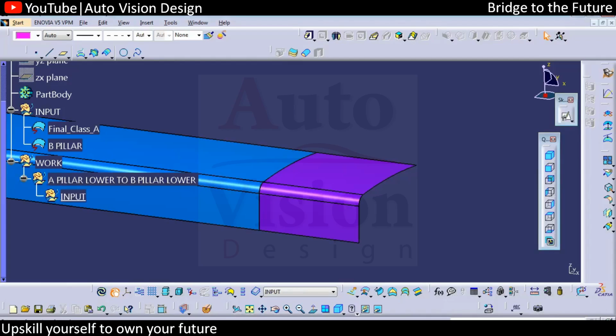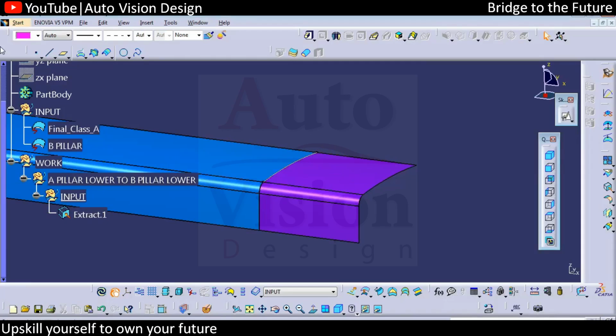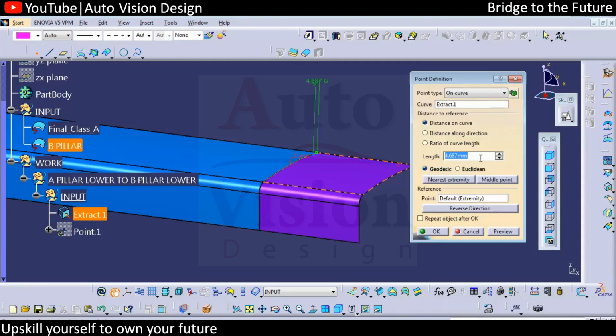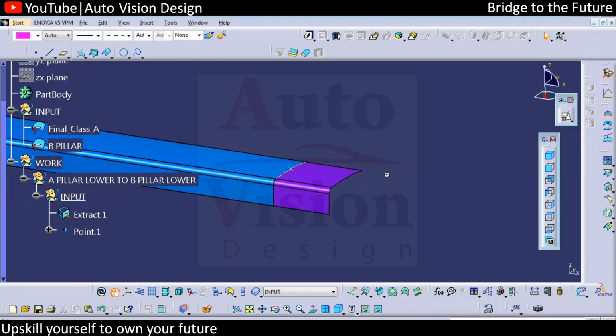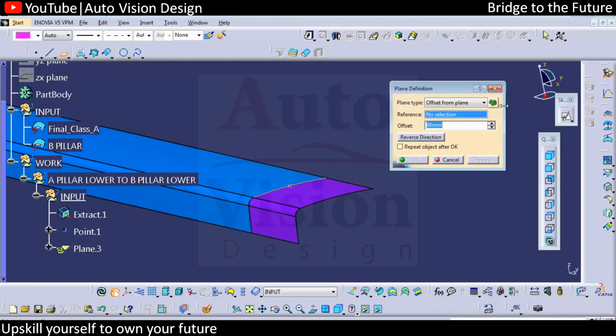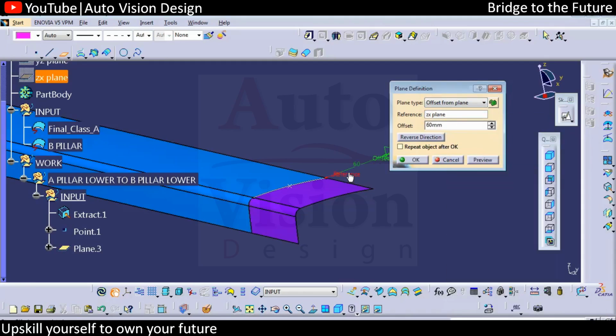In the input we're going to have the curve. So we'll select this curve. On this curve we're going to have the point, so the point will be moved, our master section will be moved. Okay, so either we're going to have this condition: with respect to a point you can control with the distance, or you're going to have the plane which will be at some distance in y. Okay, so we'll have the xz plane, offset plane to the x and z. Okay, so we'll add it somewhere here right now.